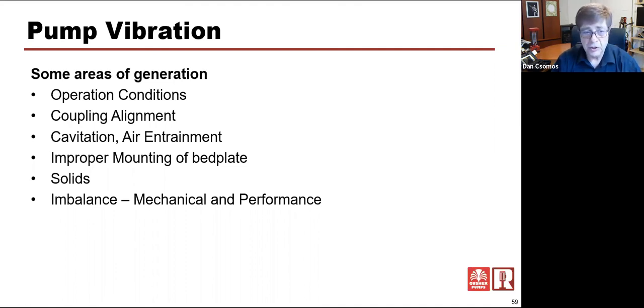What other things can cause vibration? Cavitation, air entrainment. We talked about that. Improper mounting of the bed plate. Solids going through the pump. I mean, we have pumps in the Nagel pump line, for instance, and the Gusher pump line that are meant to be able to handle solids.